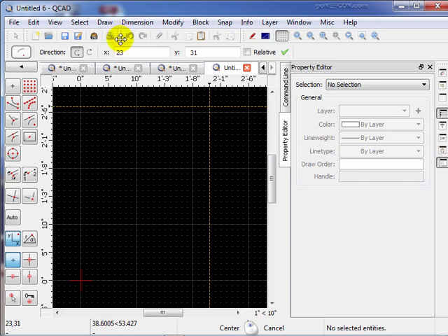So we're going to make the center fall somewhere around here, which is what, 20 something? Yeah. We'll leave 23 and 31. So you've got to click this to set that coordinate. We can also use relative values, but we're using absolutes right now. So we click this to set the center coordinates. Notice now it says, where is there a point on the arc? In other words, what's the radius of the arc? So the point on the arc will be defined in XY coordinates.